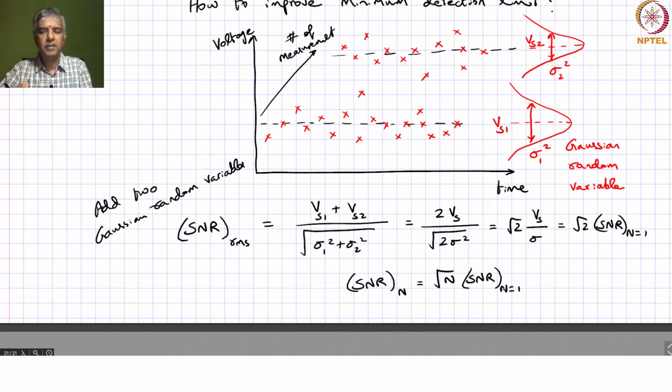So essentially you have multiple measurements, and then you take the first sample of each of these traces, add them together, take the second sample, add them together, and so on, right?